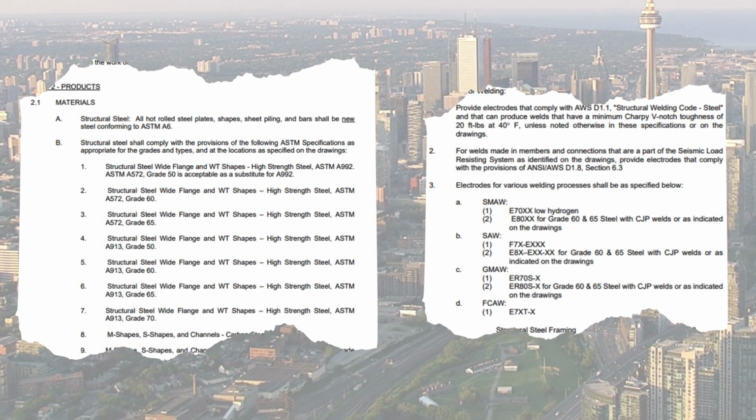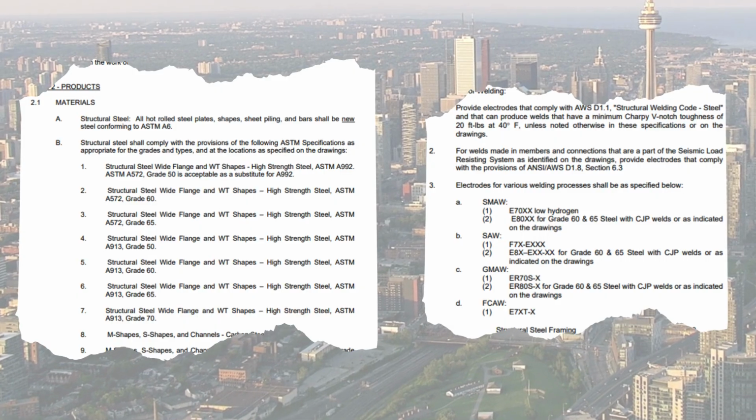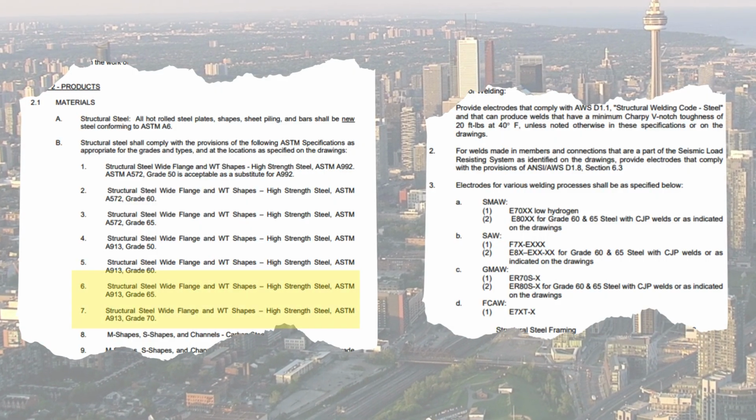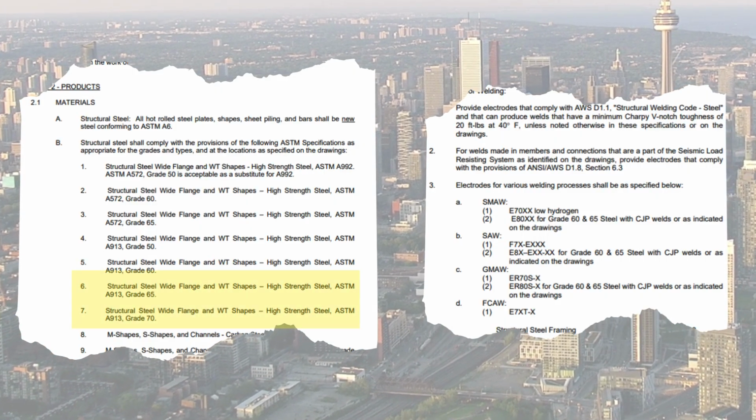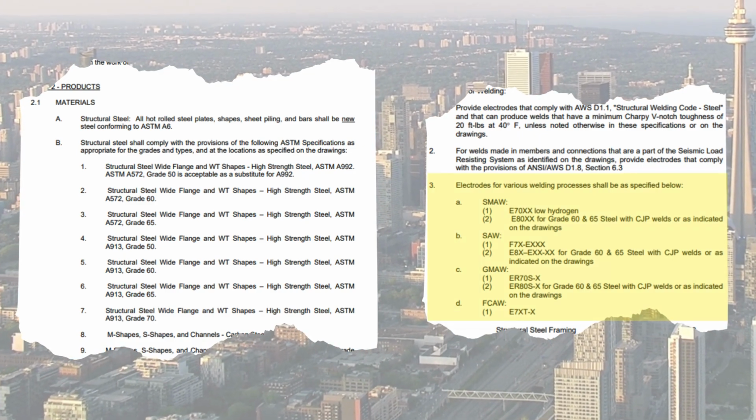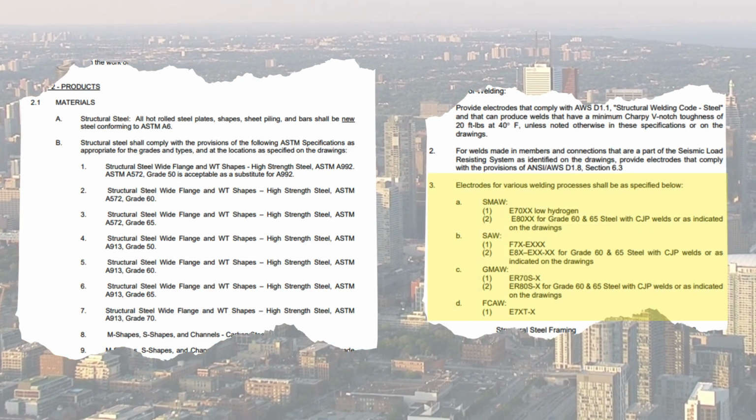The same concepts apply to specifications. Ensure all applicable grades of A913 are listed as acceptable materials, and ensure welding electrodes align with the grades of A913 that are being used on the project.